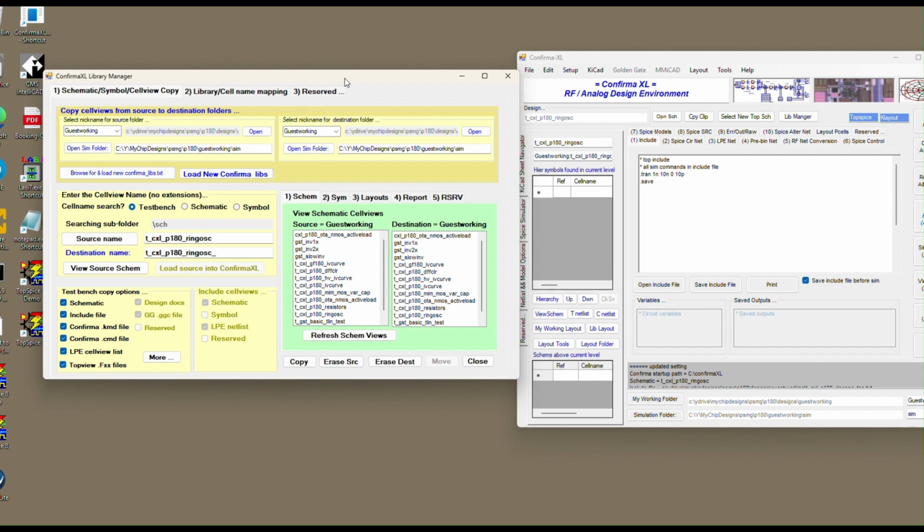And so you have basically two different types of schematics that you're dealing with in your IC design. You have the schematics that have the transistors and the foundry devices, and they represent the cells that are actually going onto your chip. And then you have test bench schematics, where you're exercising those cells to make sure that they work properly and meet your specification, and so on. So for simulation purposes, you're usually simulating from the top level test bench.